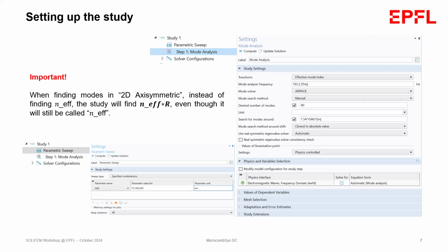You will simulate 40 modes because a lot of modes you will see yourself now will actually be calculated on the edges, in the cladding. Those modes are because the whole radii has a tight bend. There are a lot of modes which the whole structure can have. And hence it will show a lot, so we will have to calculate a lot of modes to actually get the right mode, which is inside the core.